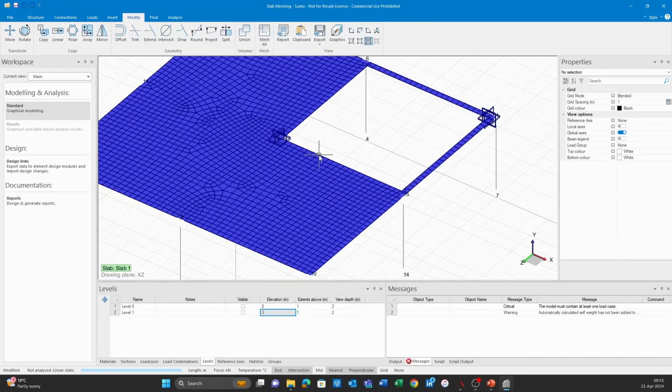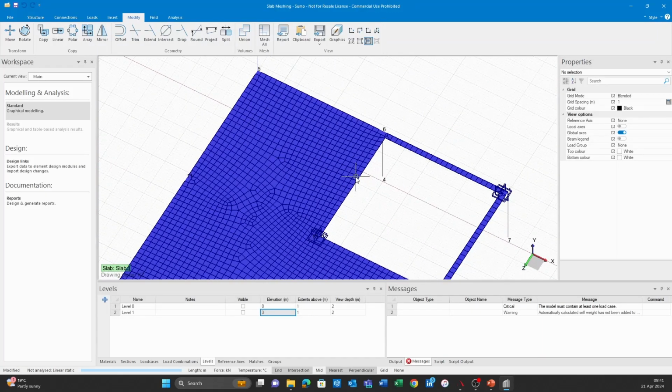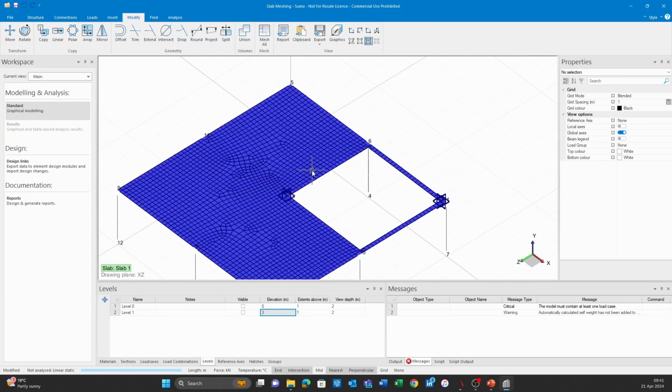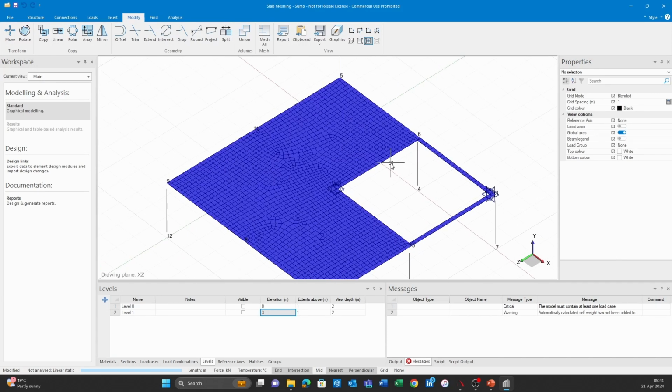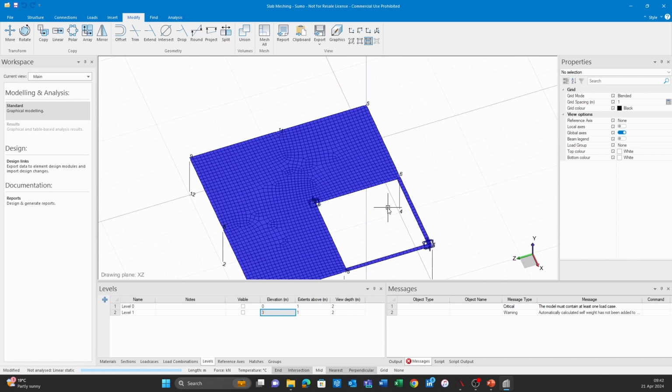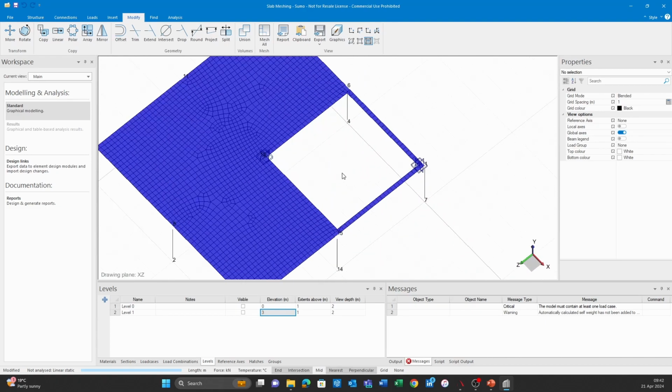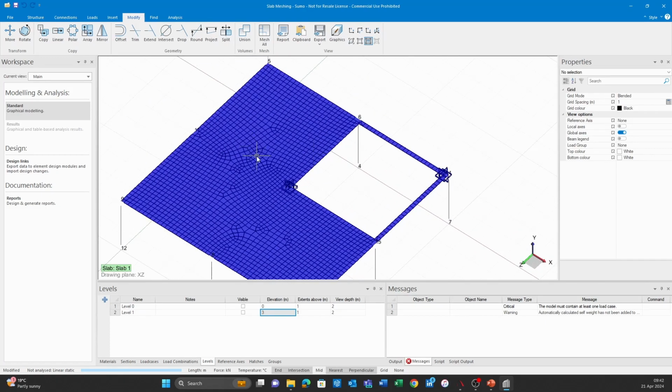And you see that this is much neater, starting to look a lot better. But this will be incredibly heavy to analyze, especially on a large model. And remember that these slabs are probably connecting to other plane shells, to walls, and that if those elements can have the same size mesh, you also save a lot of time and a lot of effort in getting that right.